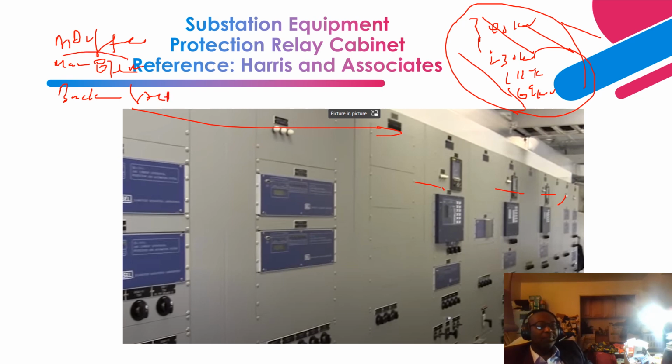That way, if this one has to be taken out for maintenance or for repairs, or if this one fails to operate during an actual fault, then you have the backup. The settings are mostly alike. It's just that sometimes they can add a little bit of time delay.